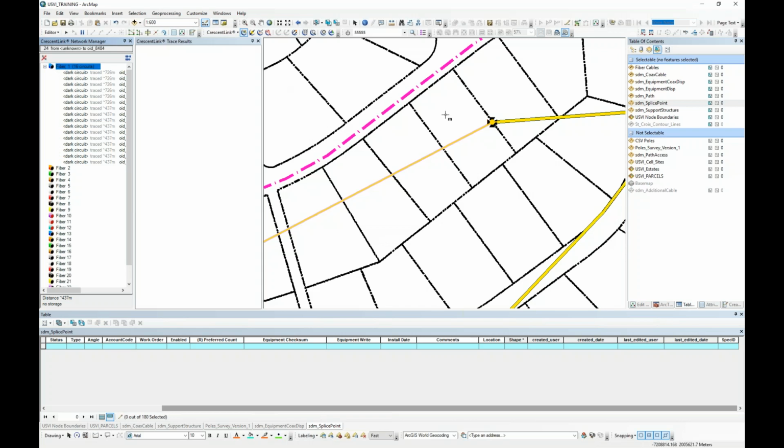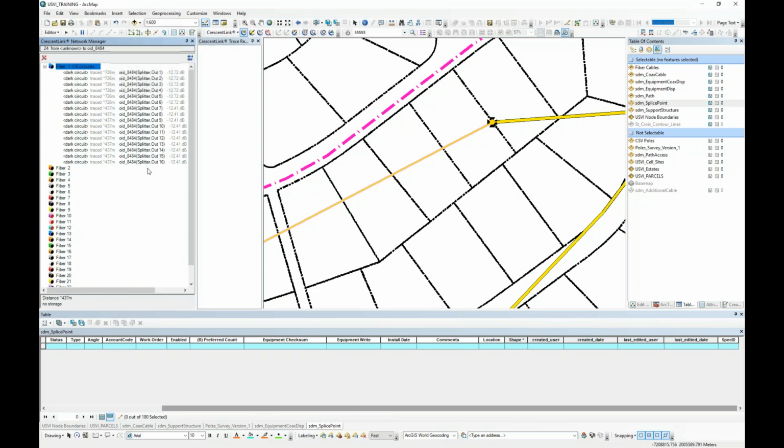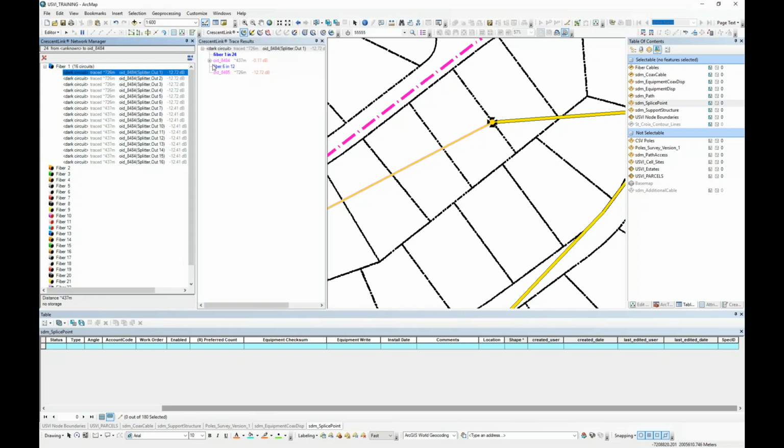Yeah, it goes straight through because the one fiber 1 into the 12, and then you can see where it comes across, so you can see what it splits to. So all the splitters. You can see based on the splitter, it carries through. So it's a more detailed splice diagram, but you would see it. And if you had all these connected out to specific customer addresses, you would see that in the details as well.